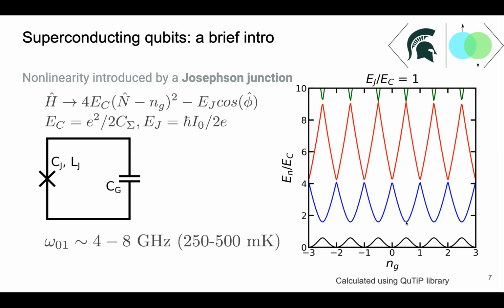And so to answer your question, Jacob, in this regime of superconducting qubits, knowing and controlling NG is very important. Because if I have an electron in the substrate, which is moving around far away from the qubit, it will dephase the qubit. And I don't really have any hope at controlling that electron.